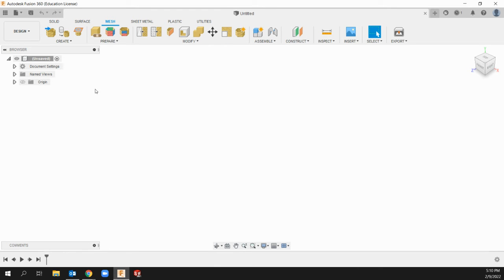Now we come to our mesh tab. So mesh has to do with the way we represent a model. This comes into play with additive manufacturing, most relatively, and it's the way that it needs to be interpreted. Our solid creates an array of triangulated areas or shapes so that math can be done. So when we would slice a file, it'll be able to read those surfaces, and that's called tessellation. So it will basically apply this surface mesh or these triangles.